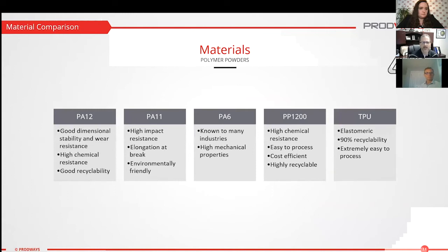So here's highlighted, I'm sure many of you are familiar with the SLS technology. It's been running the PA-based materials for some time, PA12. It's a wonderful material, well-rounded. And we talked about surface finish, and again, one of those comments about the SLS technology is grainy surface finish. For instance, to give you a reference, PA12 often runs at about a 44 micron particle size. Gives you very nice surface finish. It can have glass bead. PA11, it offers good ductility, a little more elongation as noted there.